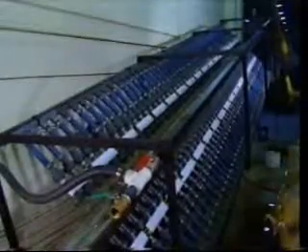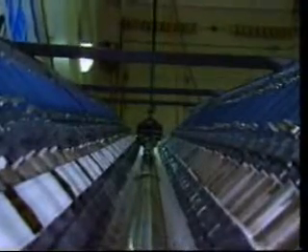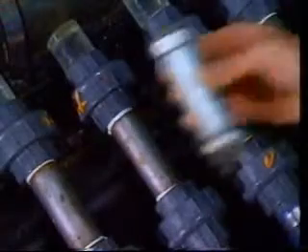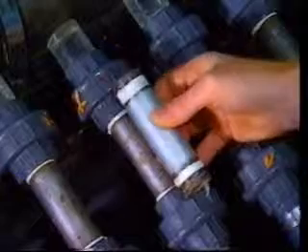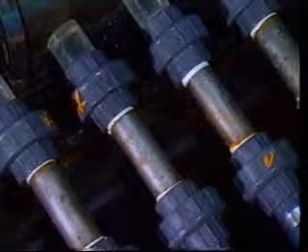We've done simulations for various operators all over the world to take a look at unique circumstances that occur downhole. For example, what happens if you have an extremely mixed lithology formation where you have numerous shale breaks in the formation in addition to both high and low permeability intervals. Now, we control the rate of leak-off to each perforation by the combination of the permeability of the core material itself plus the manifold system, which we can hold back pressure on the perforation tunnel.